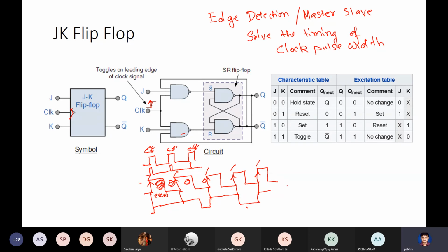So in the timing diagram of the output, the input is free. Input is the external input. It can be whatever it is, but the output is always flat. And the output is constant from edge to edge, leading edge to leading edge. Of course, if we look really fine, this leading edge is actually a small period, because this clock will be something like this. So this leading edge is actually this small period of time, but that's much smaller compared to the width of the pulse.